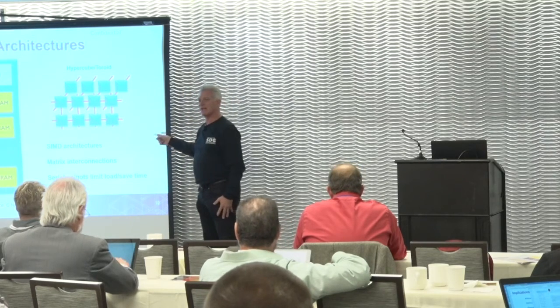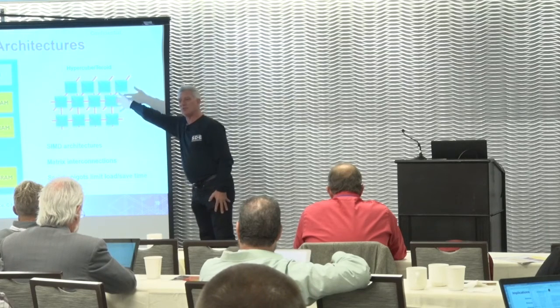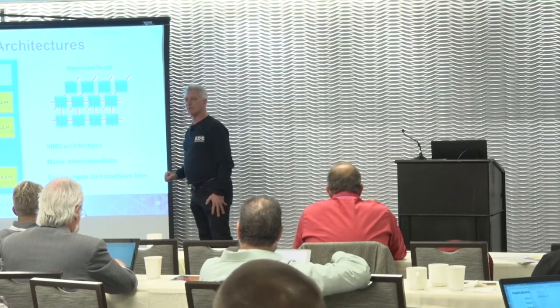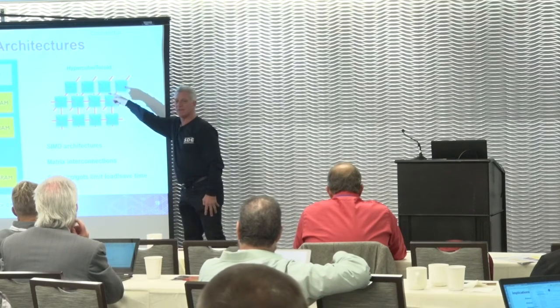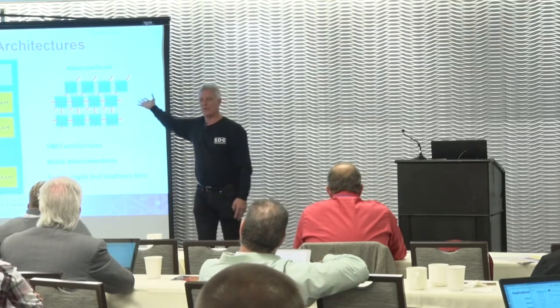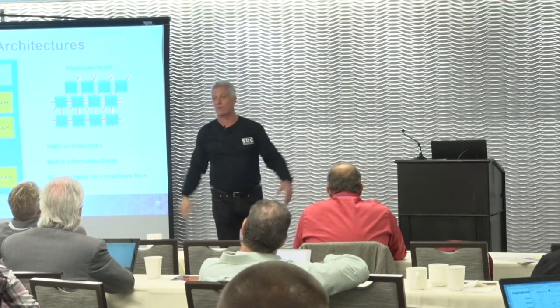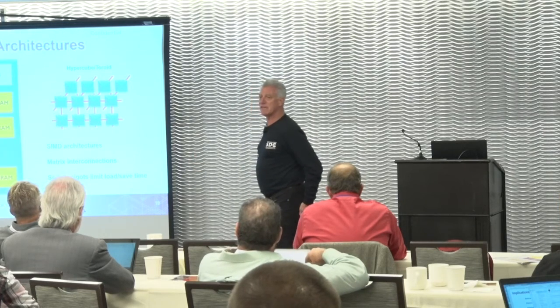And you're now going to take your memory from your SSD, load it into your cube structure. Well, that means you have to go through all these serial hops to fill each of these chips one at a time. Multiply 32 gigabytes times, say, 1024 processors, and you can see that the boot times for some of these devices can be a day.